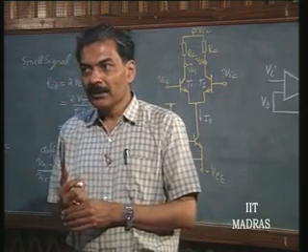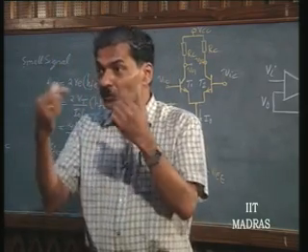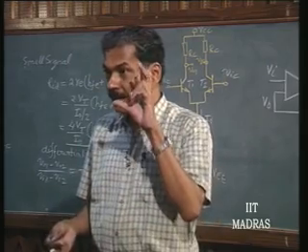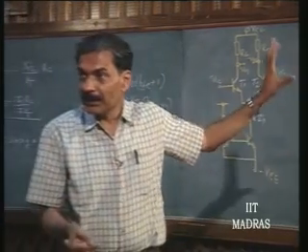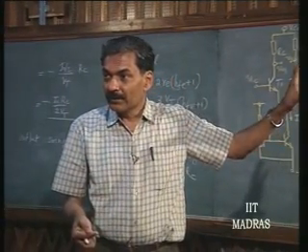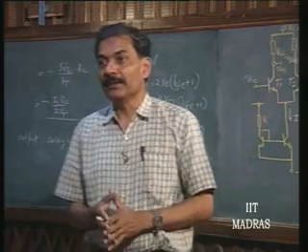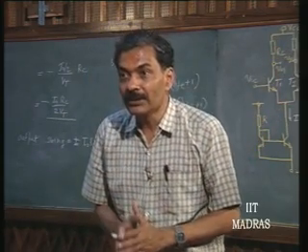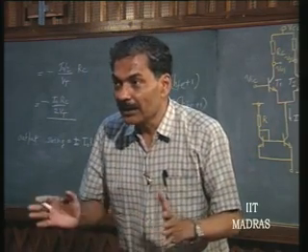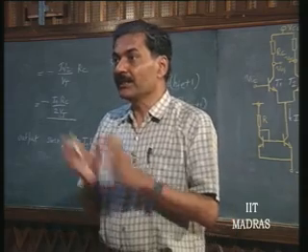That means the input common mode swing capability of an input stage which is being used in an operational amplifier is constrained to operate in this mode, as long as you are going to use it as a unity gain amplifier. This problem is very severe.